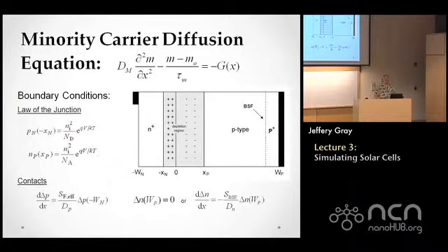Let's say in a good silicon solar cell, the diode characteristic is typically an N factor equals 1, which is your hint that you don't really have to worry about the depletion region very much. You can include it, but you don't use a minority carrier diffusion equation to account for the current generated in the depletion region. For the sake of this discussion, we're basically going to assume that generation and recombination are 0 in the depletion region, so that all the current and recombination that we see are going to be in the emitter and in the base.